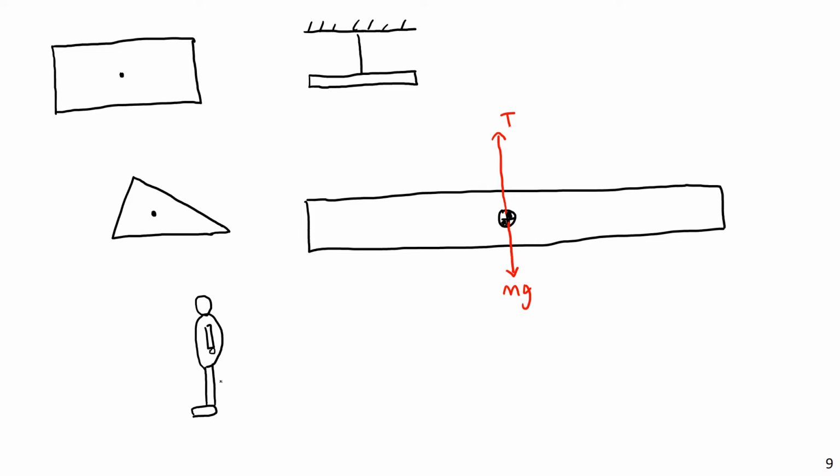And so, now, what if you want to lean forward? Let's go back. The center of mass is above the feet. And the reason for this is that your feet are the source of your normal force. There is a normal force holding you up against the floor. And your weight is acting through your centroid, which is in almost all cases in your torso somewhere, probably near your gut or something like that. And so that's where your weight is acting through.